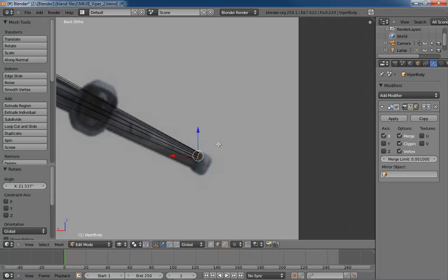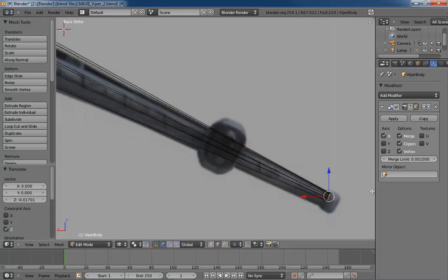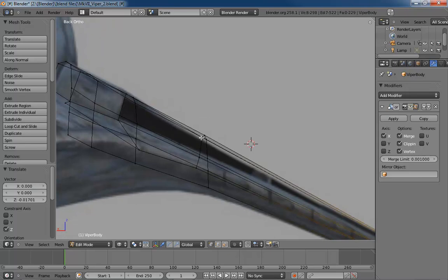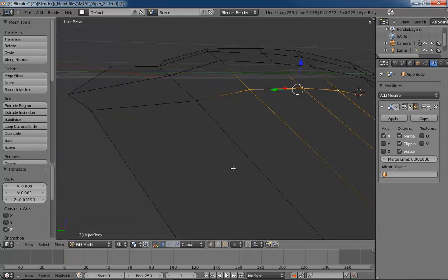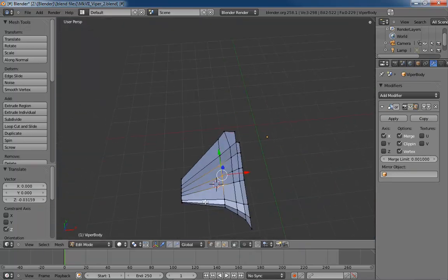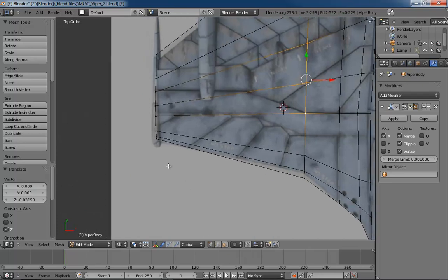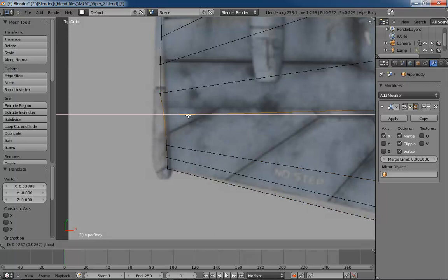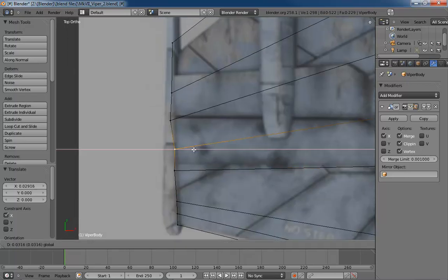We can rotate this around, and I didn't mean to do that, but we can pull this out a little ways. And that's lining up pretty well, just for a quick guesstimation. Can grab these vertices and tuck them downward, and check it out from the top view. Not too terribly much cleanup that needs to be done, really. Nothing frightening, anyway. Now, I am going to leave this hanging over just a little bit for some protrusion into that end wing piece, which I'm thinking at the moment that I'd like to make out of a separate piece of geometry, just for sake of ease.